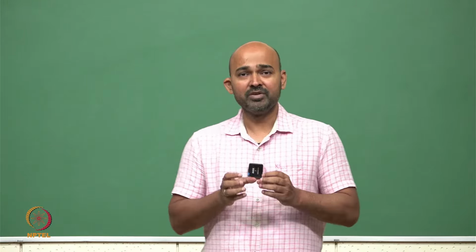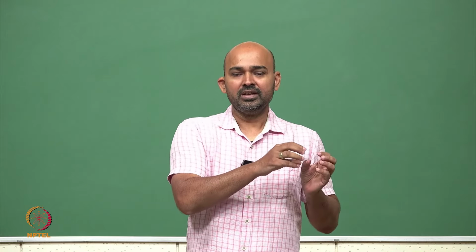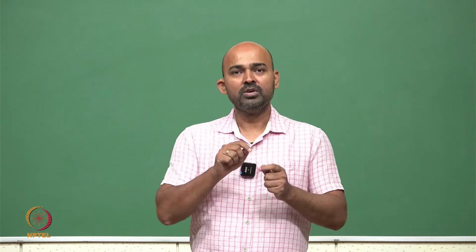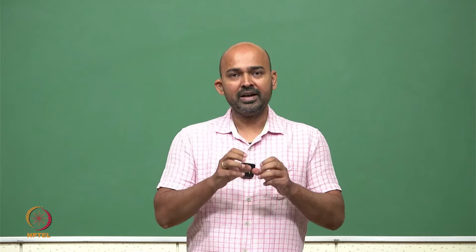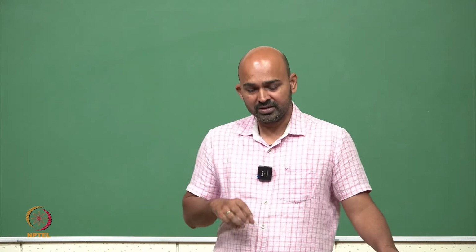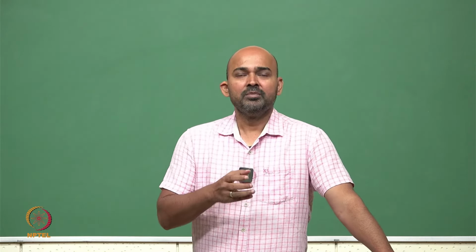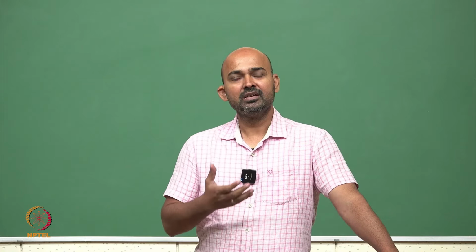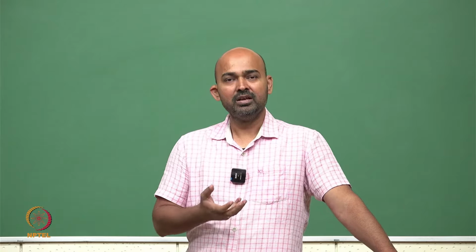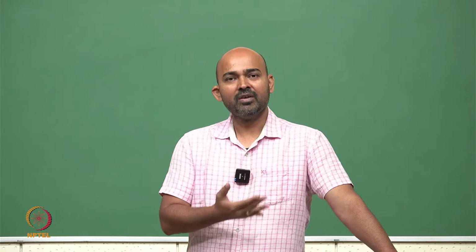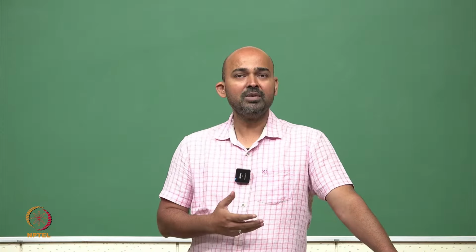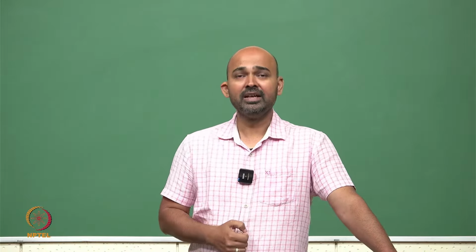For schematic design, we saw that we have a design rule or electrical rule checker where we check the electrical rules, and we have a supporting module, the symbol editor, because every device we want to put in the schematic needs to have a symbol. If it is already available in the library, we just pick it from the library. If it is not available, then we have to create it.